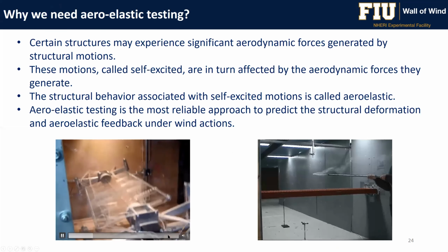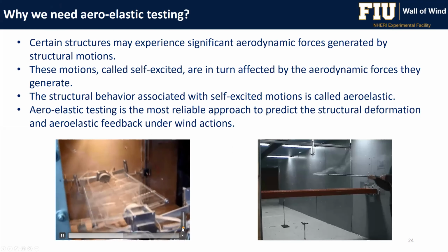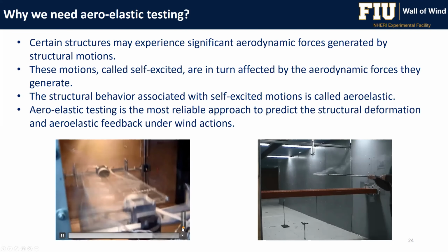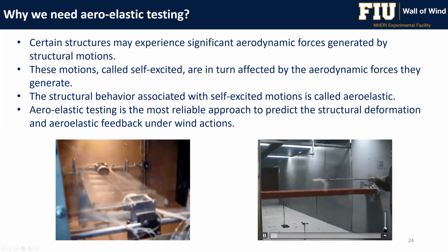So as you can see from these videos, some significant vibration will change the aerodynamic forces on the structure. So we have to consider this for something like a bridge. On the left-hand side here, we see a sectional model of the bridge. We can control the motion by side actuators. Also the same thing here, a sectional model for the deck of the bridge.